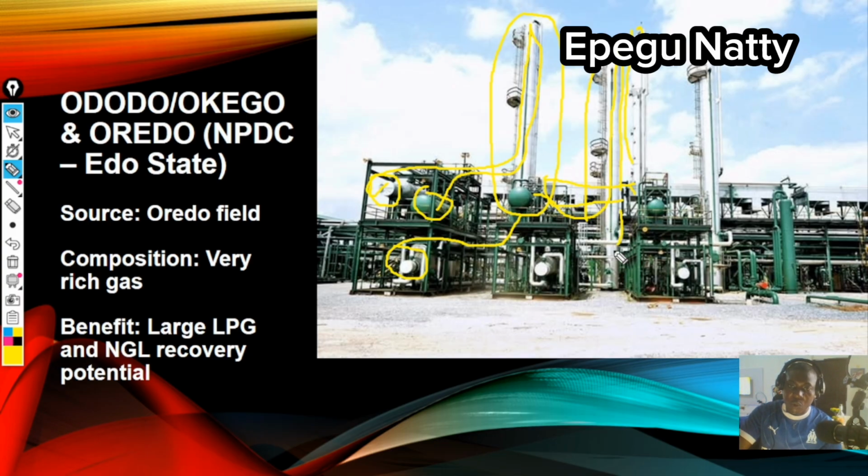And at the bottom again, we have the boiler. The boiler, the same thing, with hot oil, exchanges heat, and then the lighter ones will just go back up to the tower, and the other ones continue our journey down to the debutanizer for extracting butane also. There the butane is extracted, and the same thing happens. We have a reflux drum here, an air cooler, a reflux drum, and then the boiler is here, and from here the heavier ones continue down to the stabilizer column.